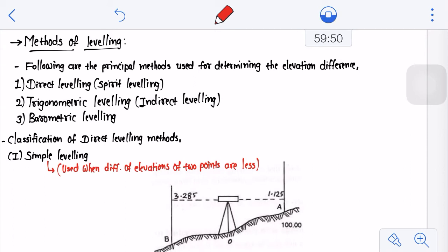The working of hypsometry for determining the elevation depends upon the fact that the temperature at which water boils varies with the atmospheric pressure, right? So the boiling point of water reduces at higher altitude, and thus knowing the boiling point of water, the atmospheric pressure can be calculated, and knowing the atmospheric pressure, the altitude or elevation can be determined.